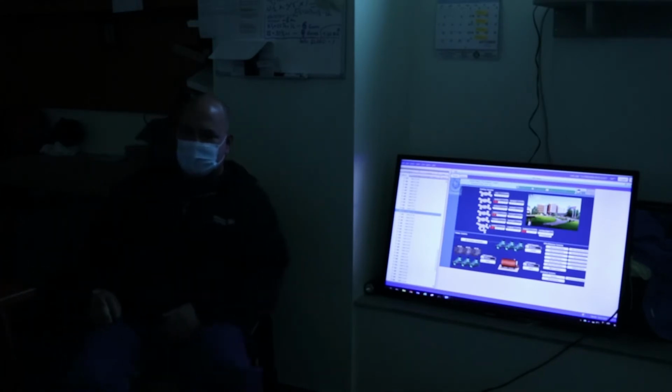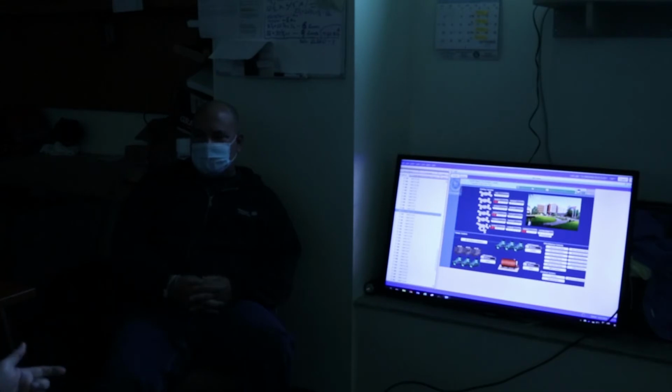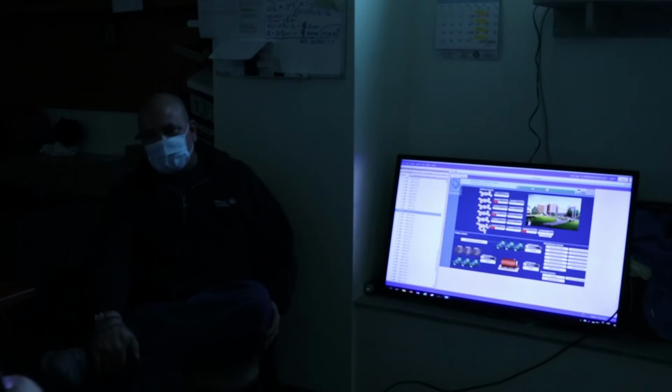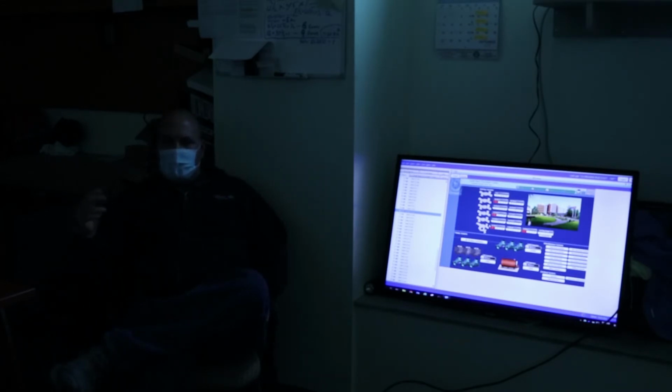Those sensors should be calibrated or no? There's no calibration. Just take one, for example, it shows like now 107, 105 degrees, doesn't matter, right? And I come with a physical thermometer and the temperature showing me 70 and I feel it's 70, not 105. It means one needs to be taken off and another one installed, right? Most likely, if it was set up right from the beginning, but it could be that the wrong sensor is defined in the software.